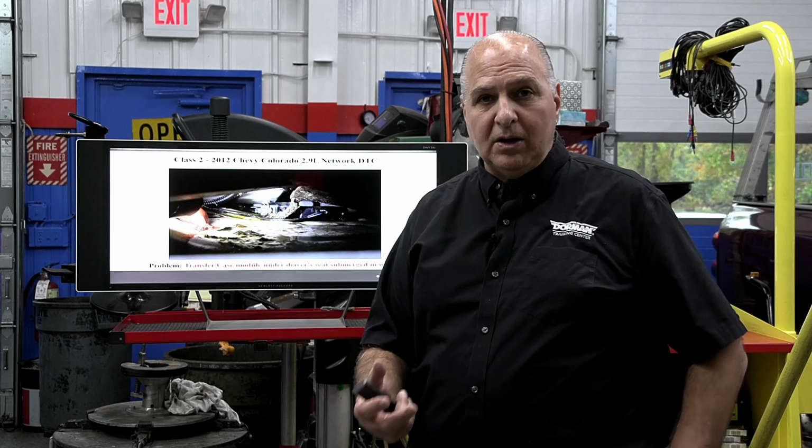Always clean drains out in vehicles and moonroofs. Make sure you open them up, trunks, clear all that junk out of there. We have vacuums here in every bay. I put that in the article, air vacuums. Get that junk out of there because the water will go in like it did here, and guess what? Of course, we have to dry it up, find the source.